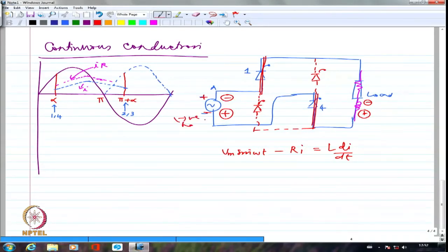Now, because this is a short circuit, this positive is applied automatically here. And because this is a short circuit, this negative is applied automatically here. You get my point? This is positive, this is automatically applied here, and that is negative. Through device number 1, it is automatically applied to the cathode of device number 2. So that device is forward biased.